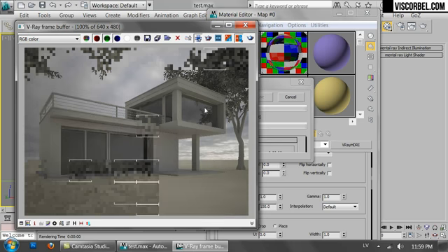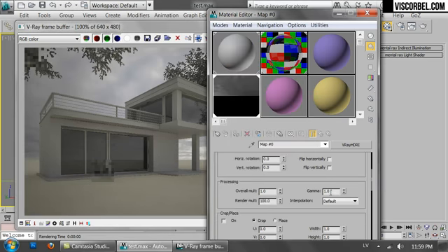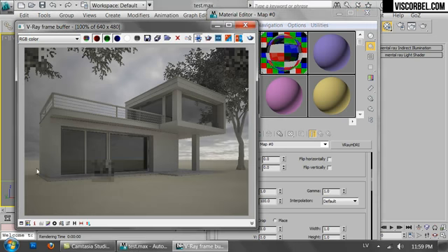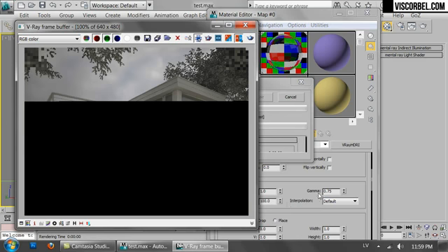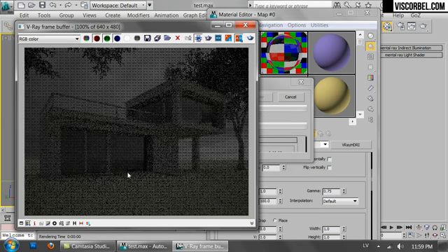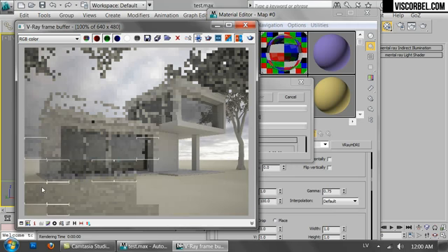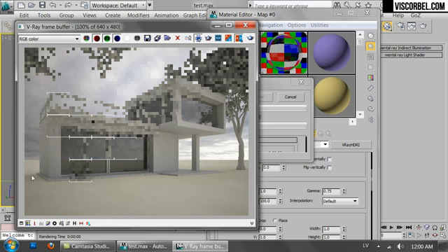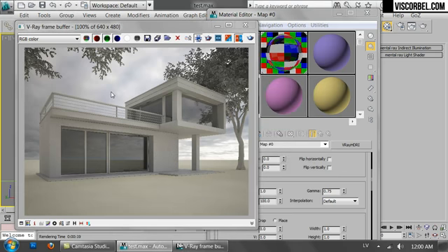And I think the sky looks a bit flat, and we can increase the contrast by reducing the gamma value. The shadows are a bit too soft as well, and increasing the contrast of the image is going to help with that as well. So let's say we're going to reduce the gamma to maybe 0.75. I found that values from 0.5 to 1 work well. I wouldn't go lower than 0.5. Okay, that's a bit better. You can see that the shadows are a bit sharper as well. And the exposure looks about right.